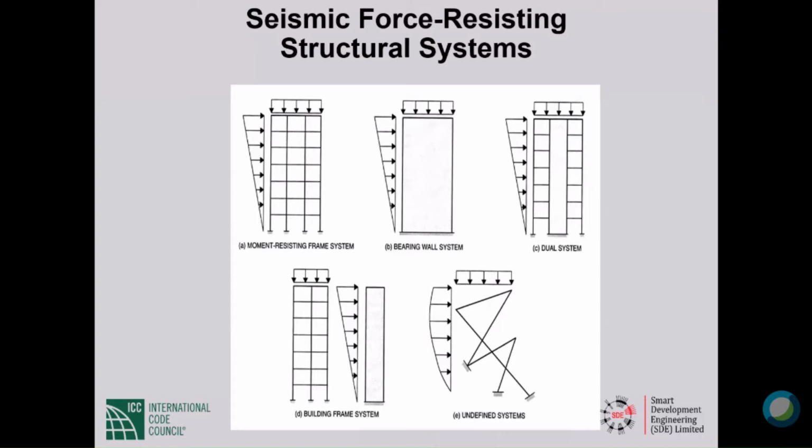In a building frame system, we separate gravity resistance from lateral resistance. We have to have essentially complete moment frames carrying substantially all the gravity. The words essentially and substantially are both important. I didn't just throw them in. The frame has to be essentially complete, not necessarily 100.00% complete. And substantially all the gravity loads have to be taken by the frames. That doesn't mean the weights of the shear walls have to be carried by the frames.